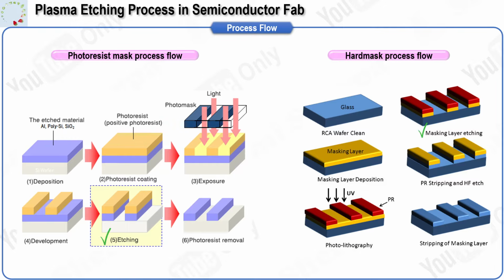The patterning sequence is as follows. Write the image and resist on top of the hard mask by lithography. Open the hard mask with a short selective etch that minimizes roughness and controls the top corner. Apply a trim if needed to tune the critical dimension by a few nanometers and to compensate for optical bias from lithography. Strip the resist and clean the surface to remove native oxide or polymer, for example a brief hydrofluoric acid clean before an oxide transfer or a dilute sulfuric peroxide clean before a metal transfer. Use the hard mask to drive the main target etch with stable sidewalls and long overetch capability.